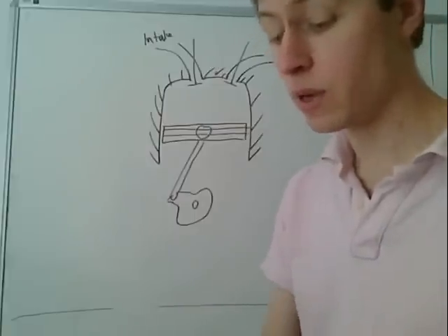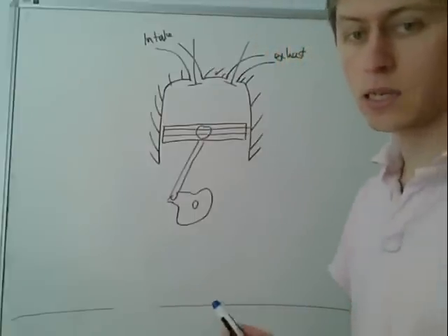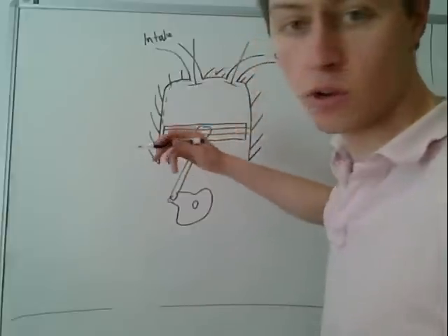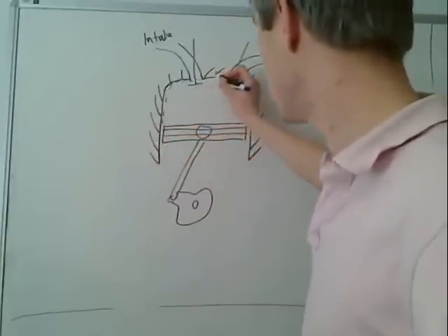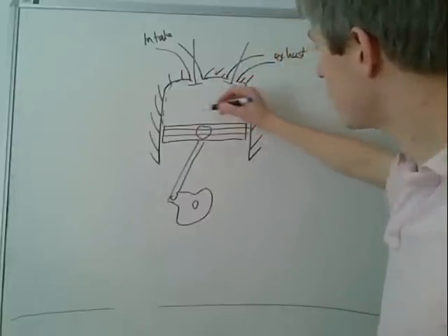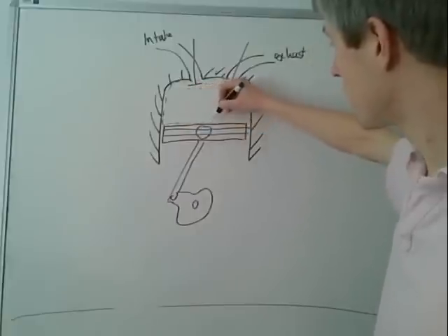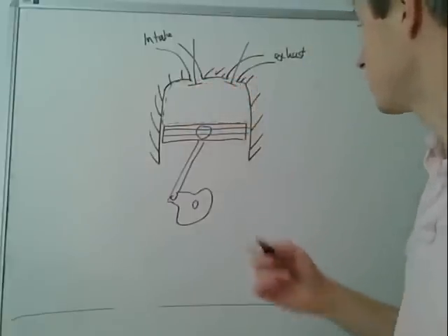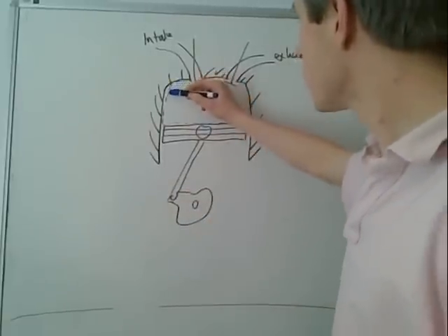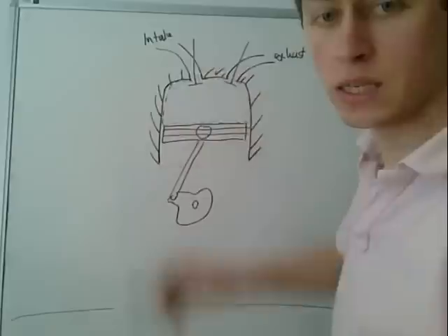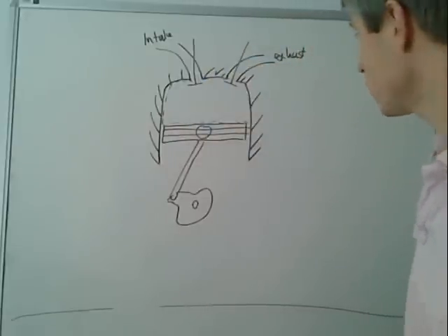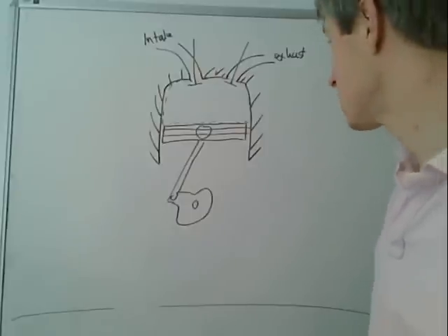So what I suggest might be useful to do is to have a system that just contains gas, and you could do that by having the system boundary go along the inside of the metal here to cut across the valve ports here. And now the piston is moving, but we could have a moving control system or control surface. So we'll just draw it along the surface of the piston metal. So now we have an only gas system. When the valves are open, it's an open system. It's exchanging mass.